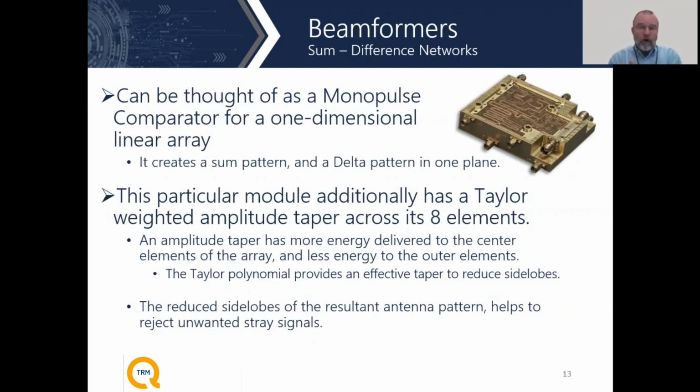It is normal to want to reduce the side lobe levels as much as possible, and maintain the purity of the data coming from the particular direction you're steering to. So from an application standpoint, we almost always want to maintain very low side lobes. Aside from actually designing the individual antenna apertures themselves for lower side lobes, you can further decrease those side lobes by applying a power taper across the aperture.